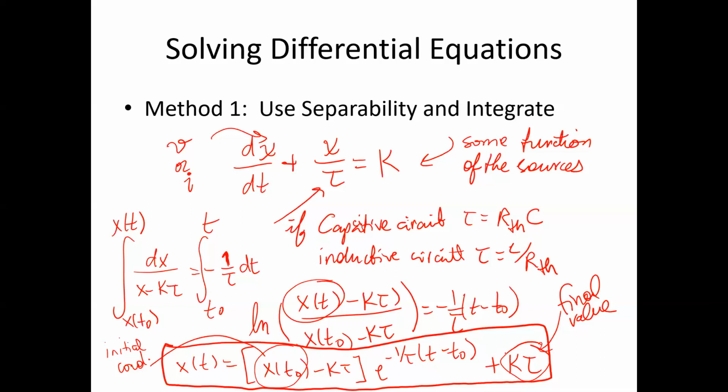And once you know those values, the only other thing that you need to be able to write this dynamic equation governing how the voltage or current behaves in between the endpoints is to know what the value of this tau here is. And the tau is a very special variable. It's known as the time constant. And as we'll see when we get into some plotting, it'll show us how fast the circuit either dissipates or how fast the capacitor charges.